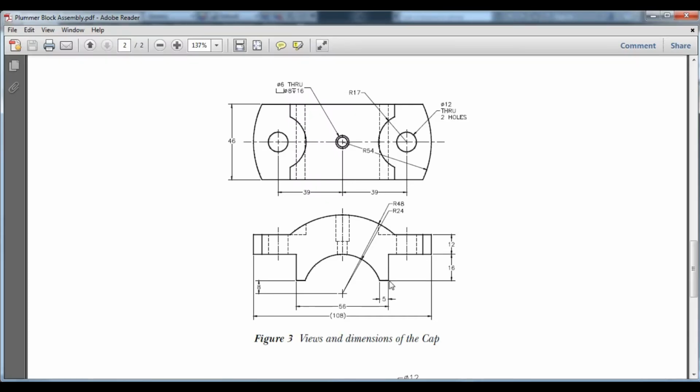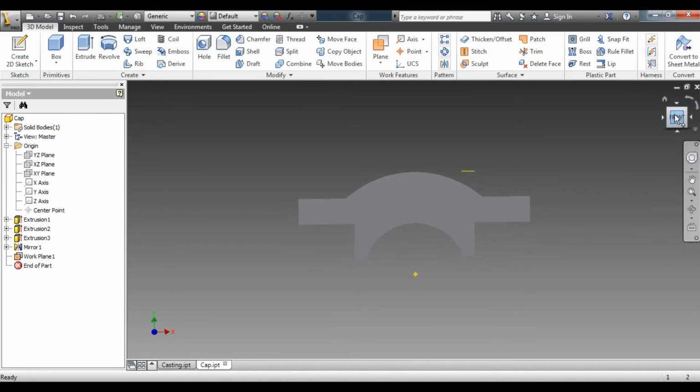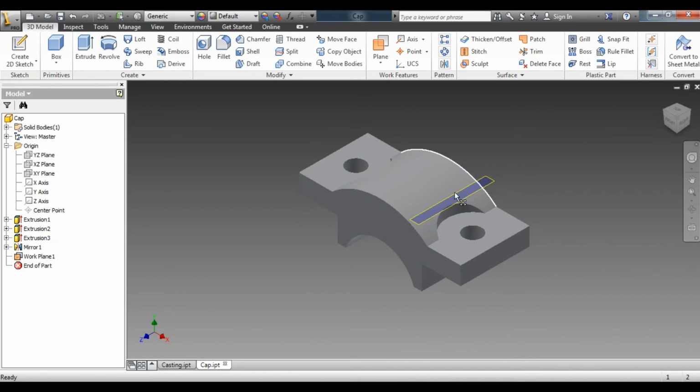I select the plane over here. Okay, so the total is 48. From here to this point, the distance is 48 minus 8, that is 40 mm. So for the new plane, the direction has to be changed, meaning it is minus 40 mm. Okay, now the new plane is generated, and the plane is here. Using this plane I will construct the hole.